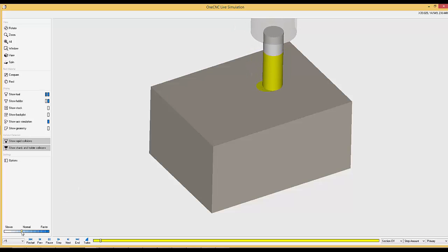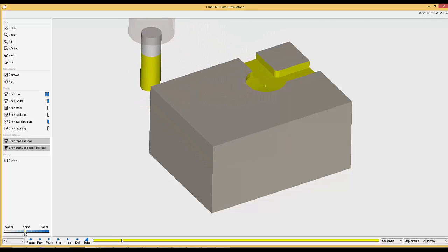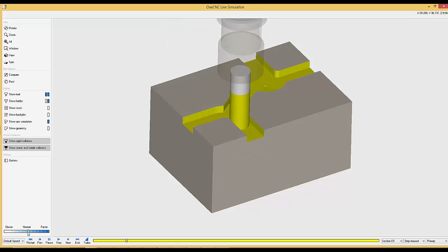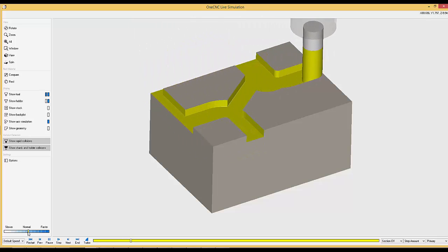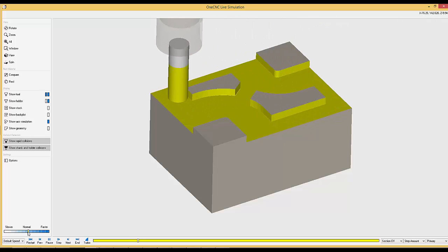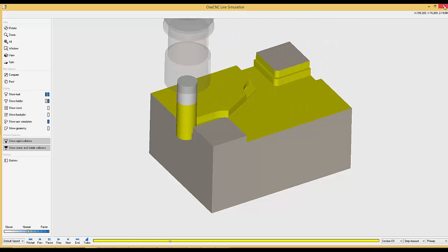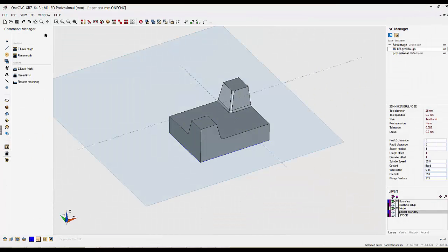Okay, so now we're doing a nice safe entry, helical. Tool again is doing full channel cutting at this point and some fresh air around the profile that doesn't need to be done, again wasting some cycle time. So we'll just carry on and push through the first level of this toolpath. It's now radially profiling in at its 50% step over. Let's see the difference when we do this the Professional way.